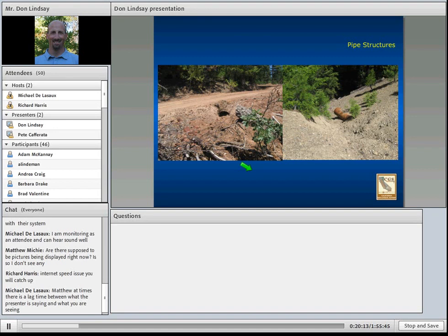By this, I mean this is the grade of the ditch or road. The fall on the pipe, or the grade of the pipe, needs to be 2% greater. The pipe on the right daylights in the fill slope and has scoured a channel below. To improve this installation, it appears that it would be best suited to receive a downpipe that would extend below the toe of the fill slope.